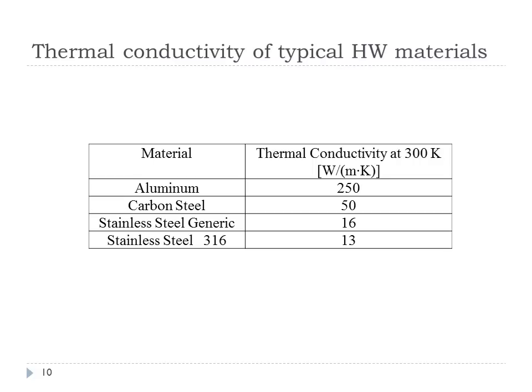I want to give some values that you can use. Point out that aluminum has a very, very high thermal conductivity, which is nice because it means that you can keep down the area of the heat exchangers. It has a value of about 250 watts per meter Kelvin. Carbon steels have a decent value of thermal conductivity.